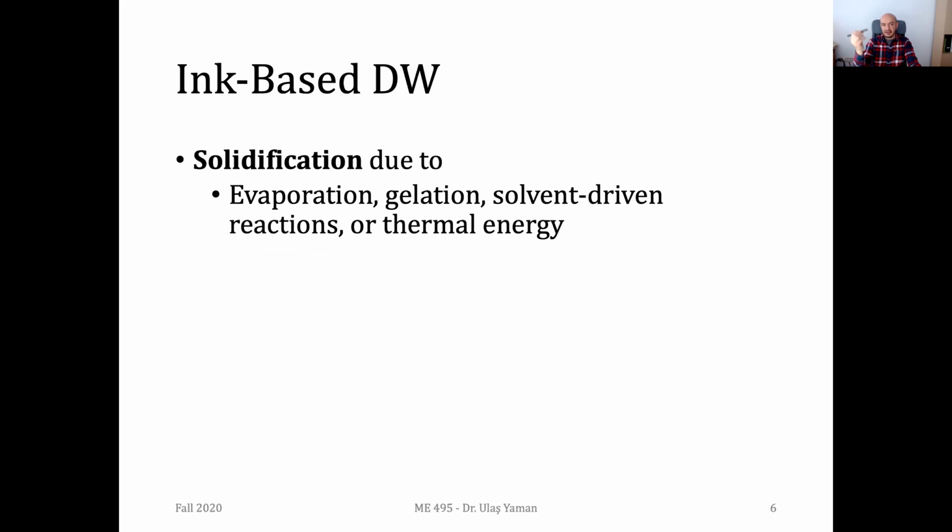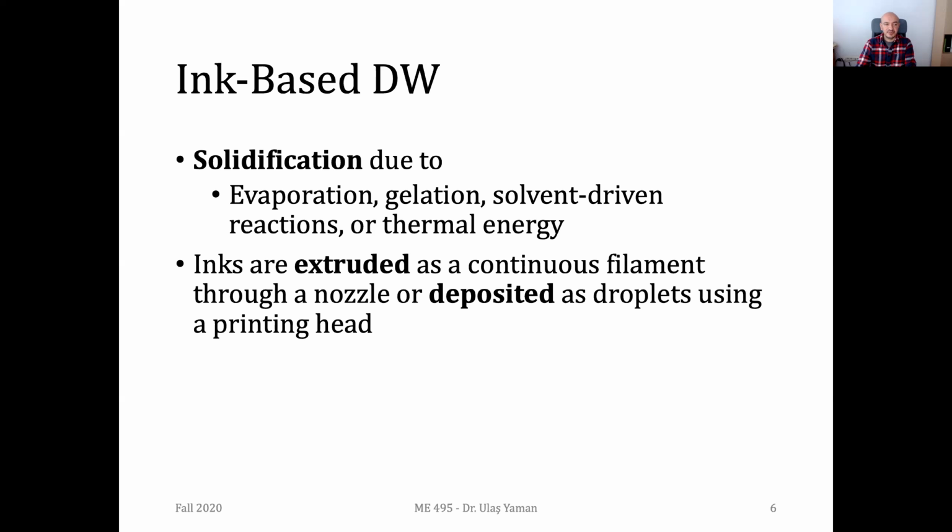Since ink is in liquid form, obviously we need to have some solidification after this ink is deposited on the substrate or on the previous layer. We can do the solidification by simple evaporation, or we may have some chemicals inside. We may do some solvent-driven reactions, start such reactions, or with thermal energy, we can do solidification.